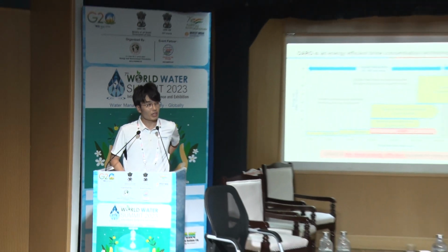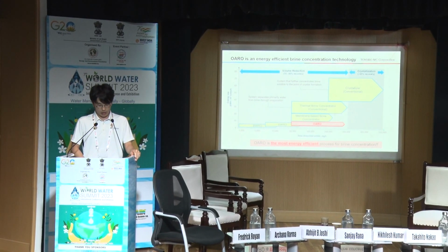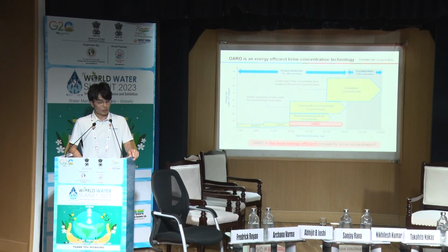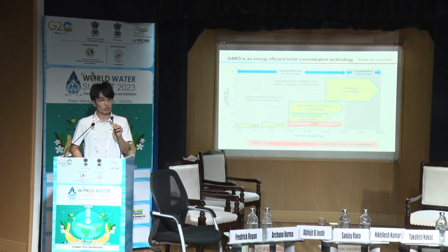As you may know, energy is one of the big challenges in zero liquid discharge and brine management technology, as energy increases dramatically with the concentration level to be achieved. Currently, membrane-based brine concentration technologies like electrodialysis, membrane distillation, and forward osmosis are challenging the thermal brine concentration technology with low energy consumption between 10 to 20 kilowatt-hour per cubic meter.